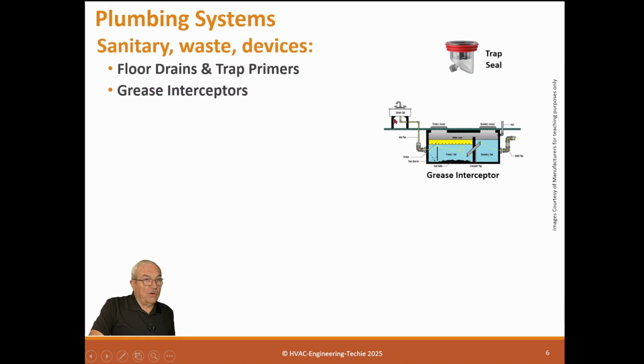And we have grease interceptors, and like I explained a few minutes ago, this is a grease trap where the water flows in, and the grease and oil is accumulated here. And then when it gets full, this water is transferred over to here. The wall prevents it from going to this space, and this tube, sometimes there are different kinds of pipes, allows the water from the lower area to enter this one. So as this gets more and more water, it will seek this height here, and this will be the oil, and the grease and sludge will fall to the bottom.